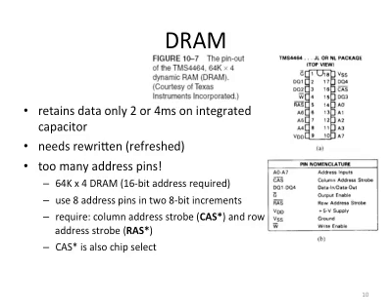With 64K locations, how many address bits do you need to access each one of these locations? It'll be 16, right? Because 2 to the power of 16 equals 64K. Think about K as 2 to the power of 10. You have another 64 times, so that's another 6.